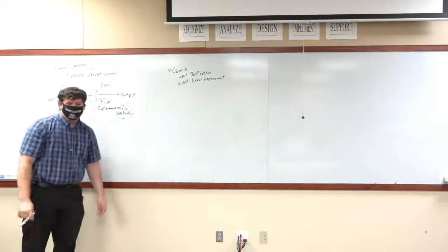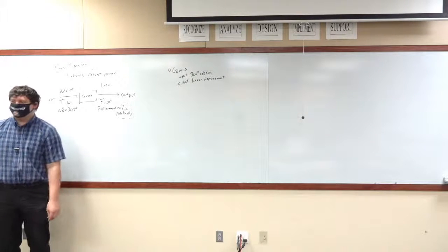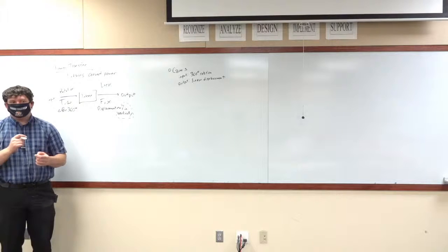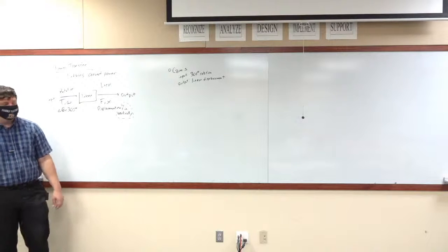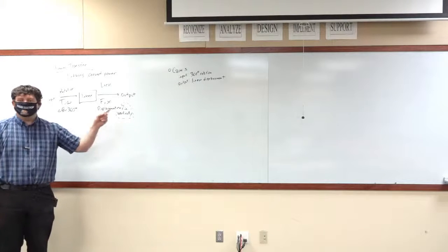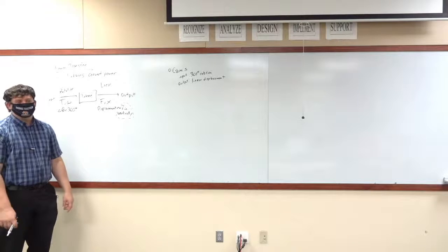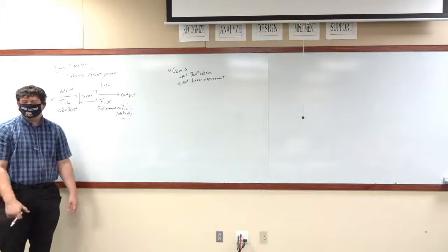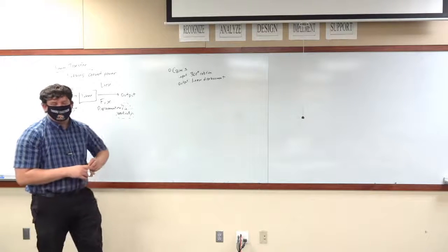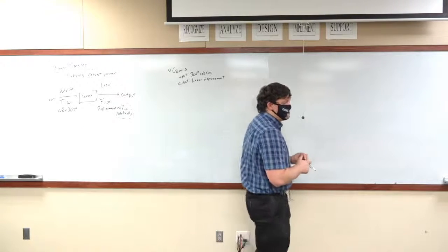Most cams have 1/4 of an inch to a 1/2 inch displacement. Why? Because it takes a lot of accelerations in a cam. Having a 7-inch displacement for a cam is ridiculous. Now you're talking to an engineer right now, well, you're listening to an engineer, I should say, who spent his PhD dissertation trying to design a 9-inch cam.